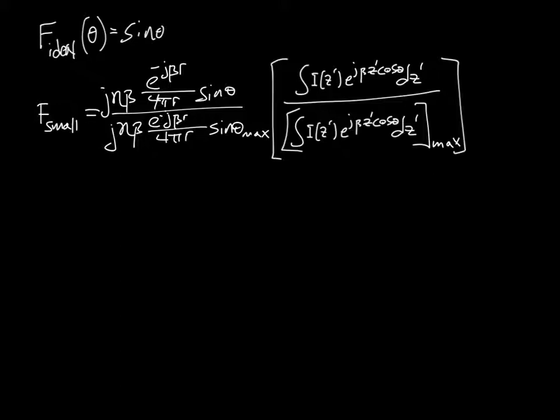And for the ideal case, this solution is called an element factor. From the beginning, we started with a particular type of current distribution that we used an infinitesimal source to find the solution for the Green's function. And the element factor is dependent on the type of current that we choose in that case and the direction.